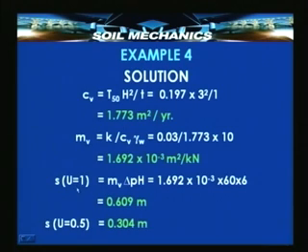settlement corresponding to 100% consolidation, that is the total settlement, in terms of mv can be expressed like this. Although I have given you the expression for total settlement in terms of Cc and in terms of e1 minus e2 by log of p2 minus p1, it is possible to express that in terms of mv as well, and mv into delta p into H will give you the total settlement.